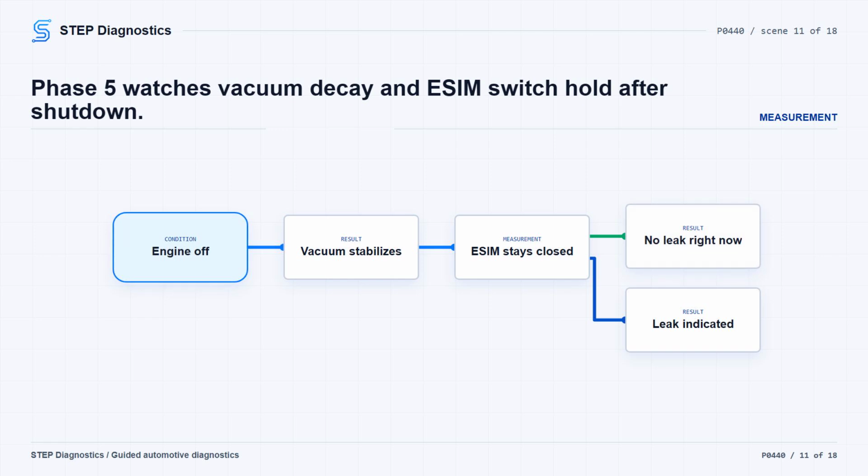If FTP rises quickly near 0 or above -250 Pa and the ESIM switch opens within the 3-4 minutes, the system has a leak, so move into leak testing. If every phase hit the expected results, the system is most likely not leaking at that moment. Possible false failures include software issues, debris that was temporarily stuck in the purge solenoid or ESIM relief valves and has since cleared, or an ESIM that is not mounted correctly with the switch at the 3 o'clock position.